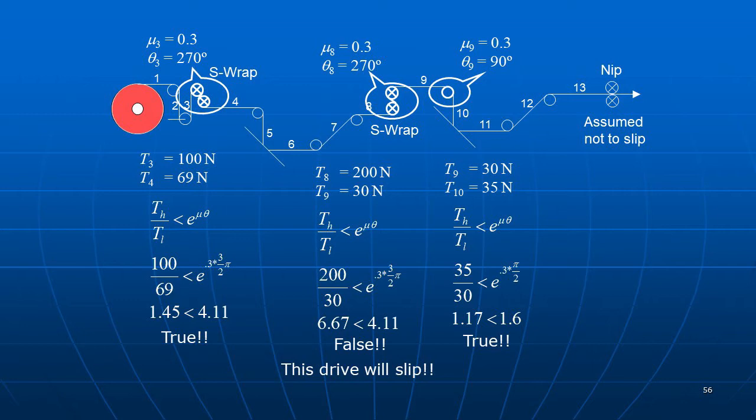So this one is definitely not going to slip. We've got almost a 3-to-1 safety factor there. And that's what you want as a good safety factor on your master roller, your references, because you really don't want to slip there, because that would upset everything downstream.